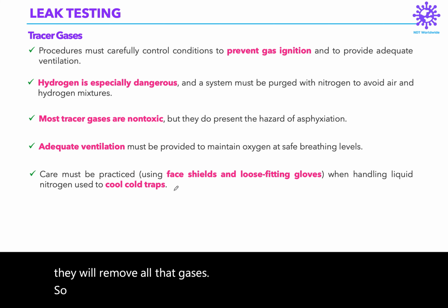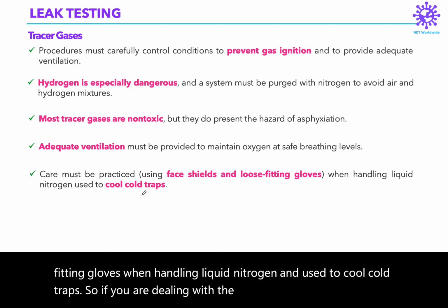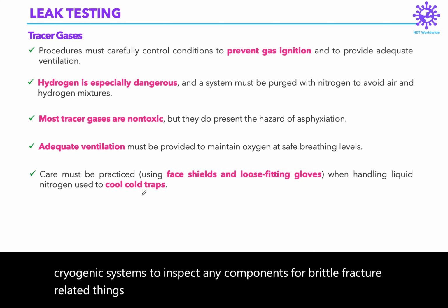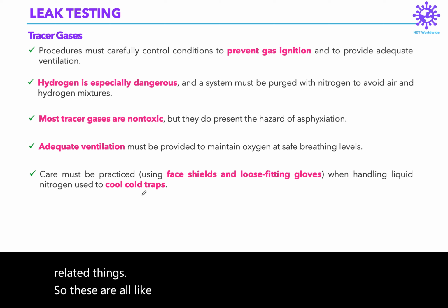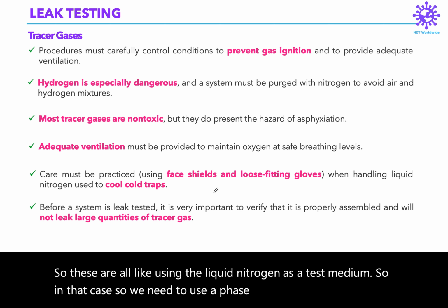Care must be practiced, using face shields and loose fitting gloves when handling liquid nitrogen, and used in cold traps. If you are dealing with liquid nitrogen systems or cryogenic systems, to inspect any components for brittle fracture related things, those are all using liquid nitrogen as a test medium. In that case, we need to use face shields and gloves.